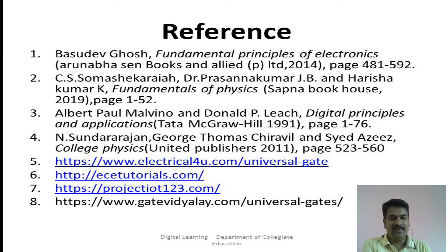This is all about today's video. We discussed the SOP, the product term, and we understood the minterm and how to write a minterm for three-variable inputs. After that we learned how to write an SOP equation for different outputs.